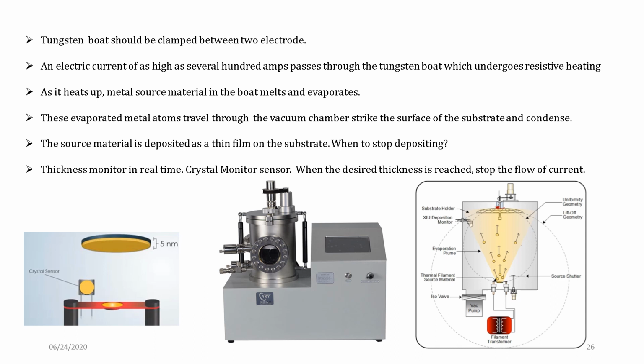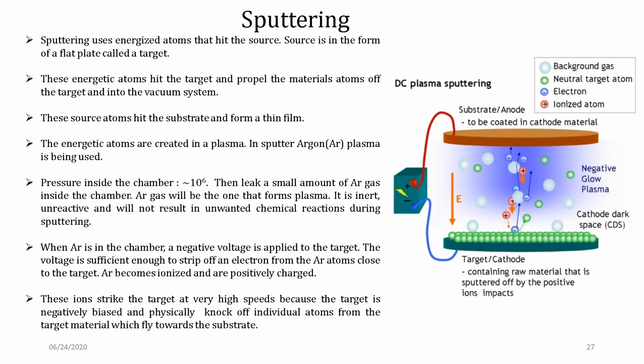We can't measure the thickness over here, but this is programmed in such a way that once it reaches a desired thickness, the evaporation will stop. That's how the crystal monitor sensor works. It just stops the flow of current. This is how a typical chamber looks.